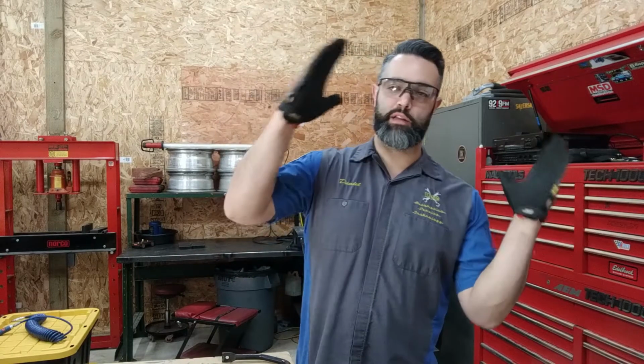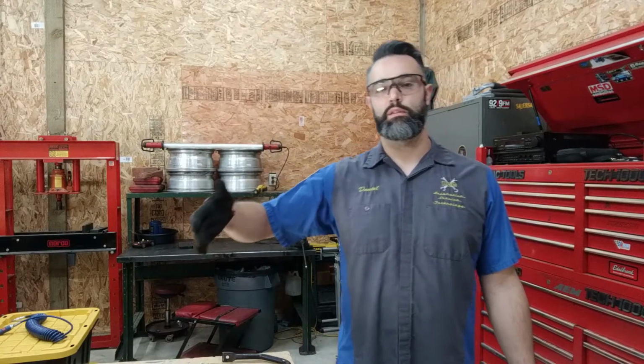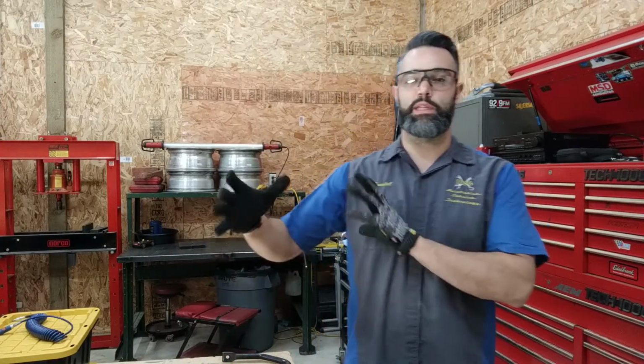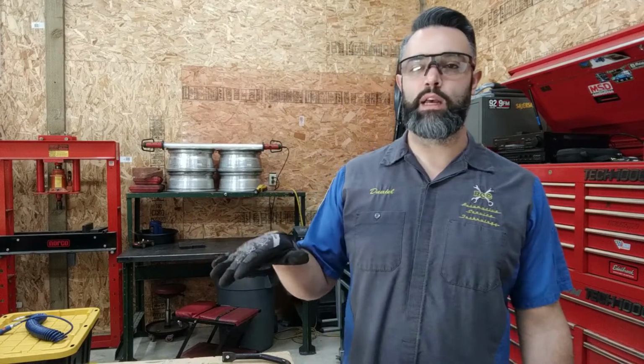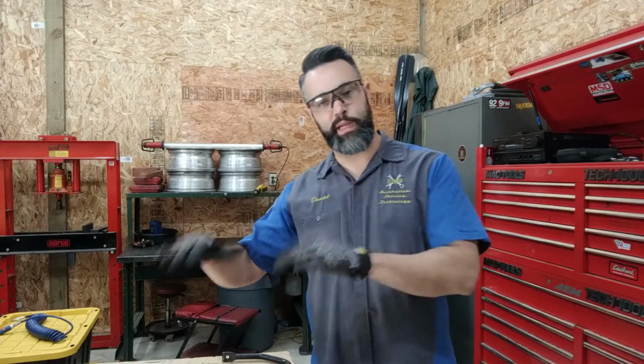off-camber situation, whether that's on a side hill or while the vehicle is making a turn, what that can do is that weight transfer to the outside of a turn is going to pick up weight from the inside wheels. And if that weight is picked up from those inside wheels, we're decreasing our contact patch between the tire and the ground and limiting the effectiveness of how we can steer, stop, and slow the vehicle down safely. Without those tires being held to the ground, we're decreasing our ability to stop and handle safely.